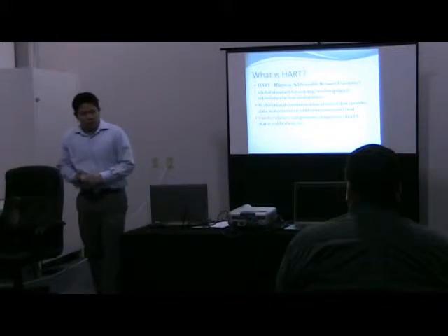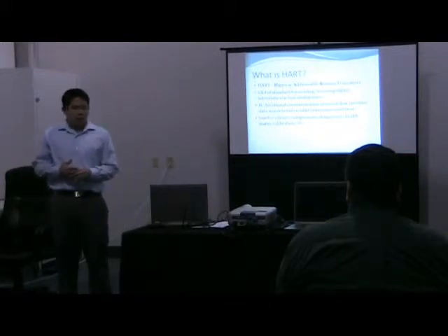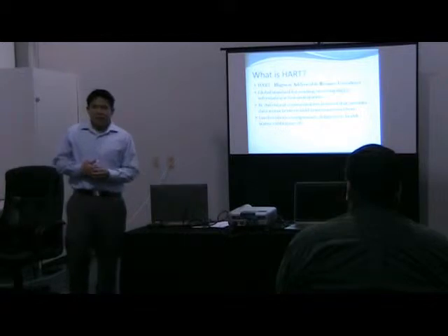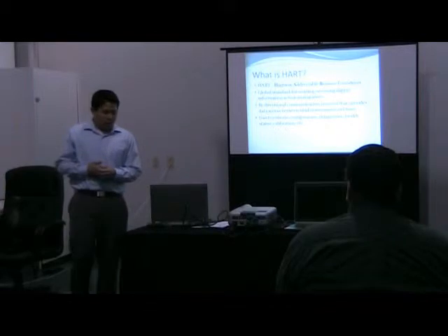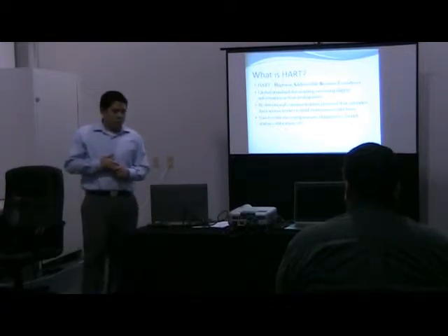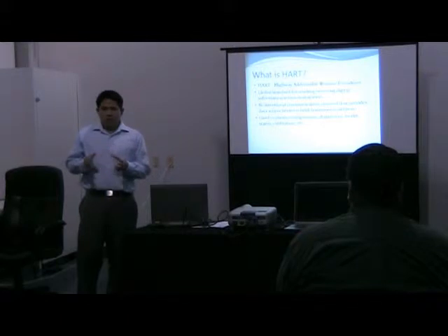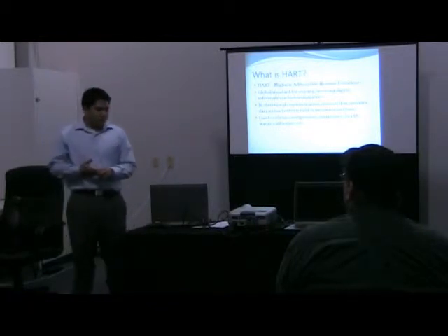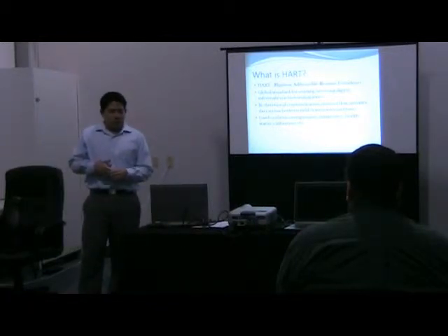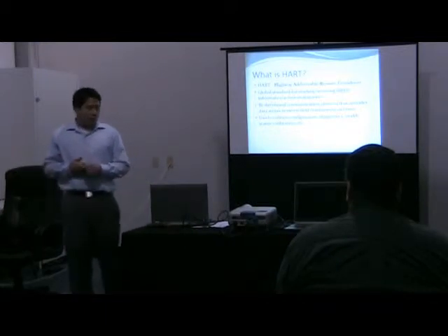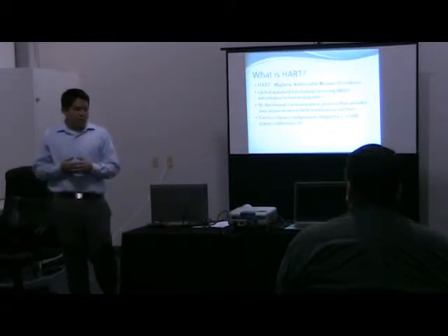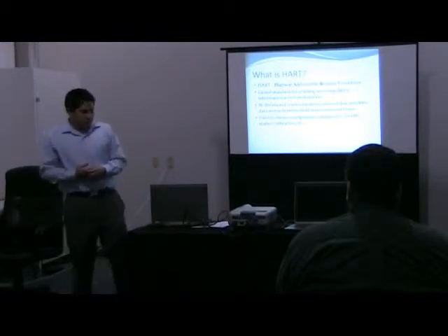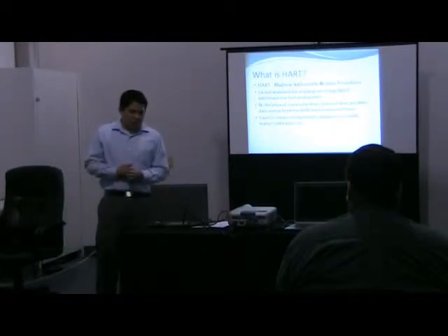So what is HART? HART stands for Highway Addressable Remote Transducer. It's become a global standard for sending and receiving digital information across analog wires. It's a bidirectional communication protocol that provides access between your field instruments and your host. Your host could be your HART device or PC monitoring system. And it's been used to obtain several types of information from your instruments, such as configuration data, diagnostics, and health status, and also to help with calibration.